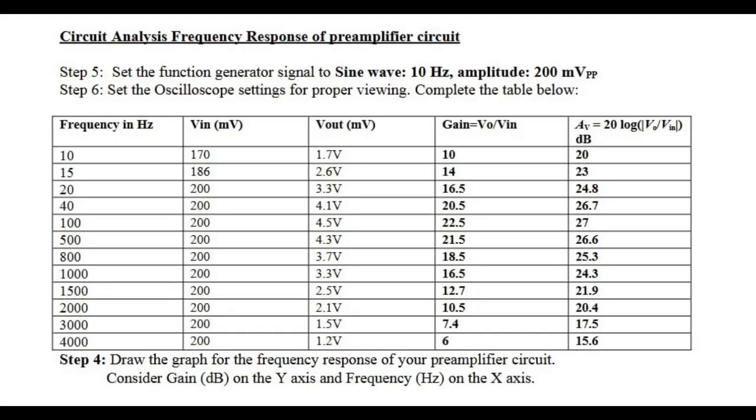Based on this table for the amplifier in stage 1, we can see that as frequency increases, the gain will also increase until its maximum of 23, as was calculated earlier on. This occurs at a frequency of 100 Hz, and frequencies higher than 100 Hz will cause the gain to drop. A gain of 23 is equivalent to around 27 dB.